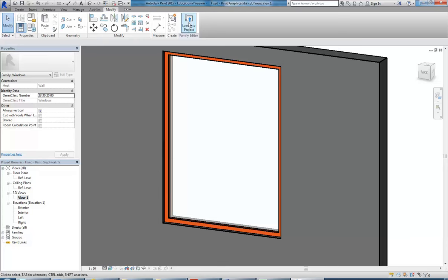Okay, so then I can do another one, exactly the same way. So I'll show you what happens if I copy this, just to finish up with this sort of basic family. If I go and edit that new extrusion, you'll see it's got the transom thickness there, because that can be copied, but it's lost that property that I set coming from here, because that can't be copied. So I've got to add in a new dimension from the sill to the base there, place it over the side, select the dimension, go to label, add parameter, and this will be transom 2 height.